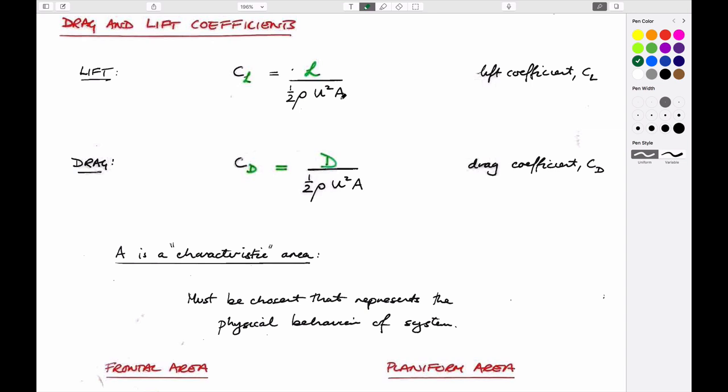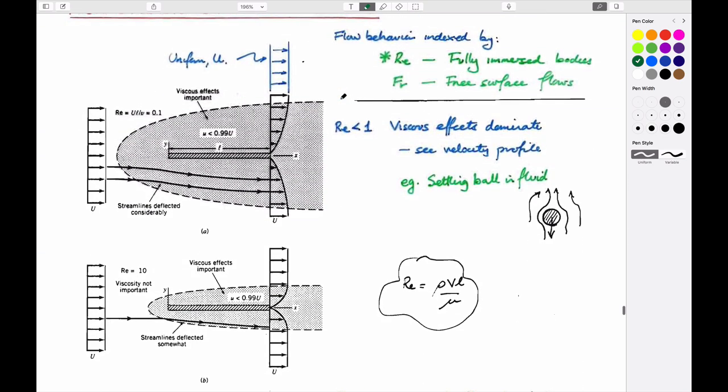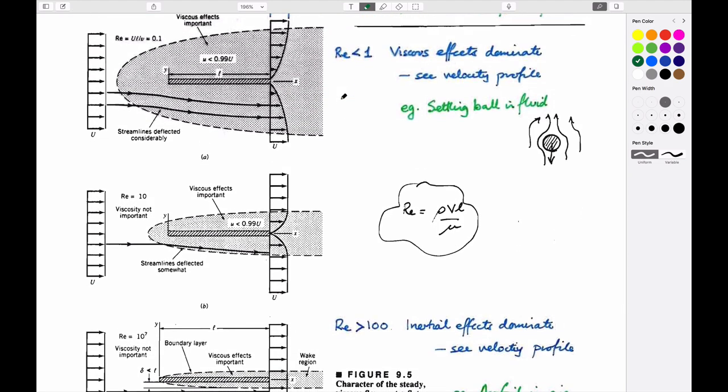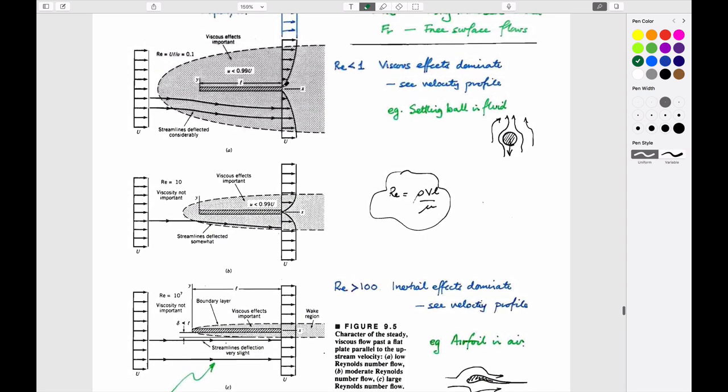So you have to choose the properties appropriately, and we can define exactly what these would be. We did an example of this. This really says, in microcosm, exactly what was happening in these figures. At low Reynolds numbers for the airfoil we looked at, as you went away from the wing, we got it to 1.6 times the external velocity. It's because it was constrained within a box in a tunnel. And so the same volumetric flow had to go in this smaller region than it did before. If it was extended to infinity, then this value here wouldn't be 1.6, it would be 1.